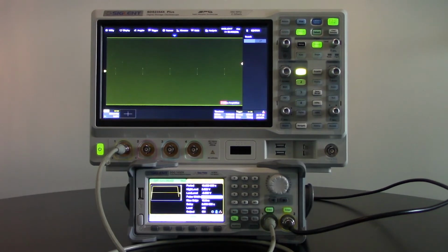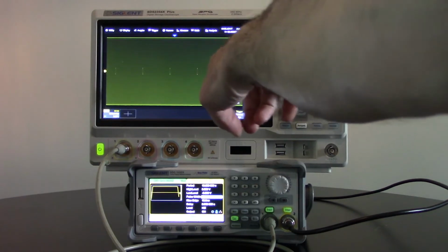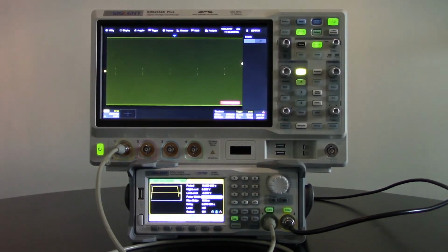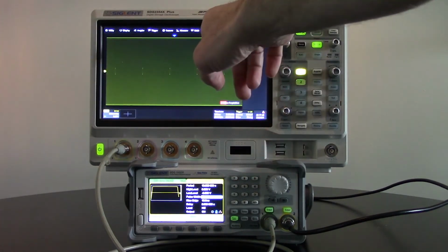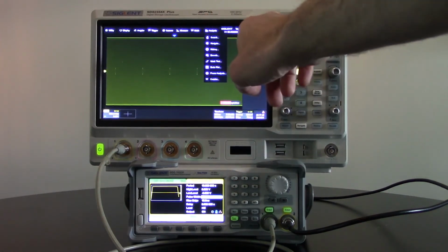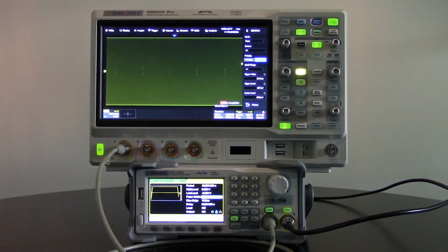Okay, now we have all of our data, and you can barely make out that there are some discrepancies here periodically. Now, again, we're doing an experiment, so I know that those are particular problems, and I could say, okay, we can just zoom directly into those areas. But what I would like to do is actually do more of a thought process here. We don't know where things are happening. What we can do with the oscilloscope is turn on the search feature. And search is really a secondary trigger.